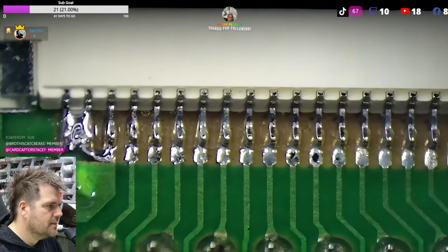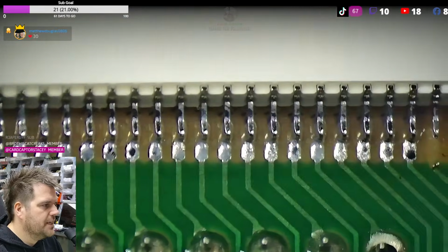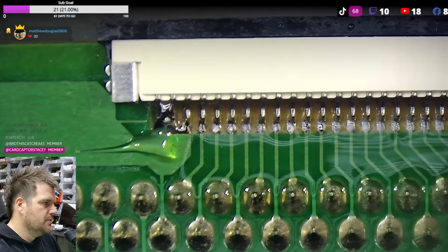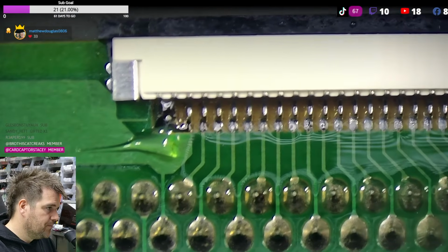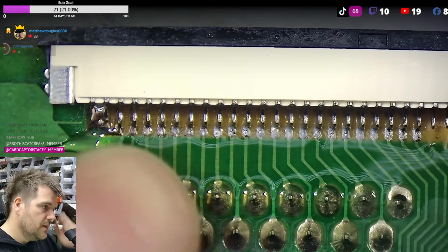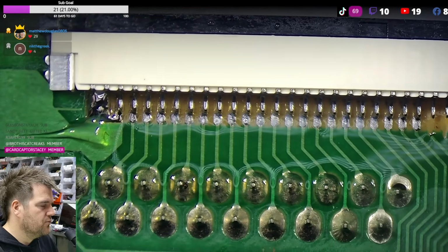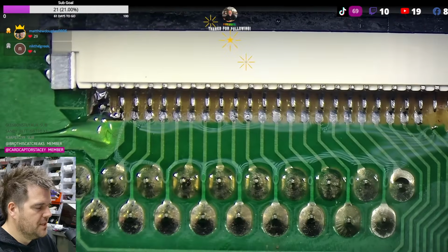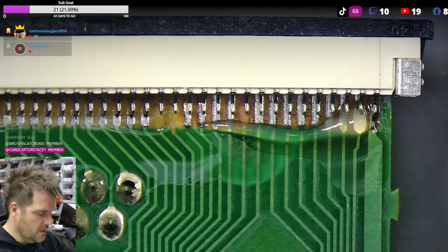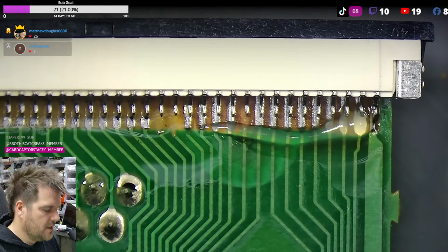So that's the technique I use on most things. It's called drag soldering generally. It's just a technique you have to practice on. But the main thing is, what I try to teach you is to not panic about touching the other pins. So many people are afraid of small pins when they go, oh, how am I going to get between that? And that's where they go down this route of getting a smaller tip. And the smaller tip makes it worse because then you've got less heat transfer and then you get shorts. So it's counterintuitive, but this is why I use a tip that's this big.